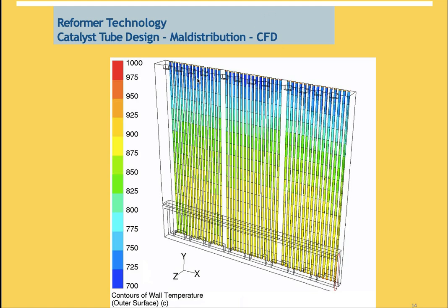Low hydrogen production from this tube, like low hydrogen purity, high methane slip at the outlet, or the PSA reduction in the recovery. The root cause can be low reformer temperature, catalyst aging, high pressure, low residence time, or poor shift conversion in R03.